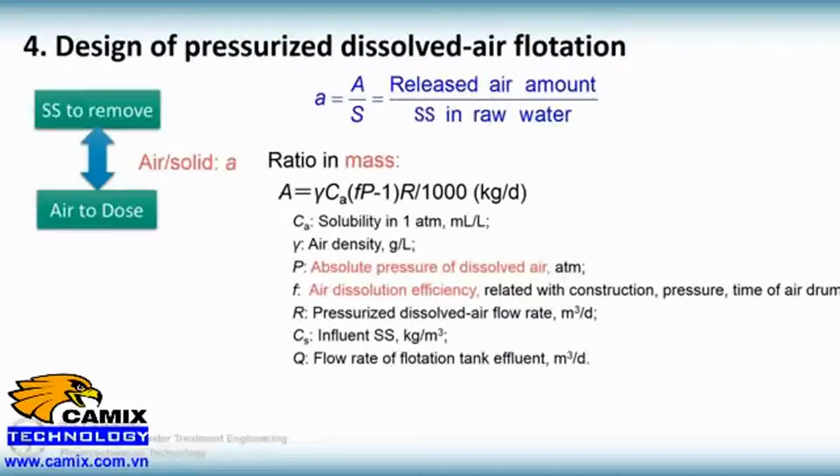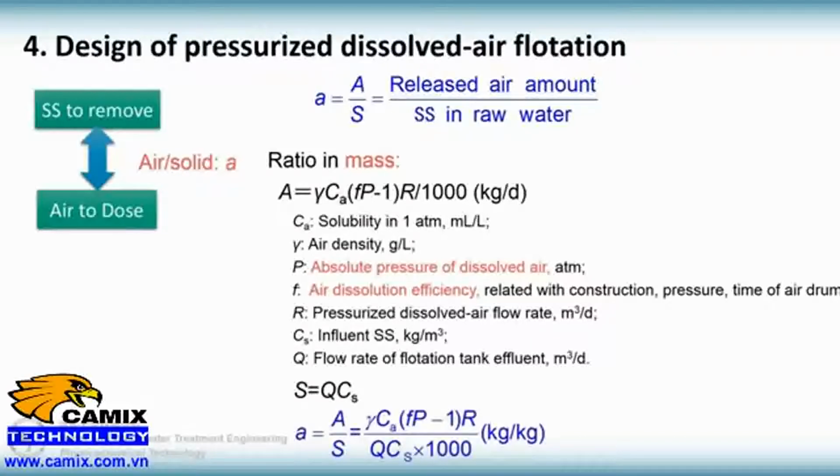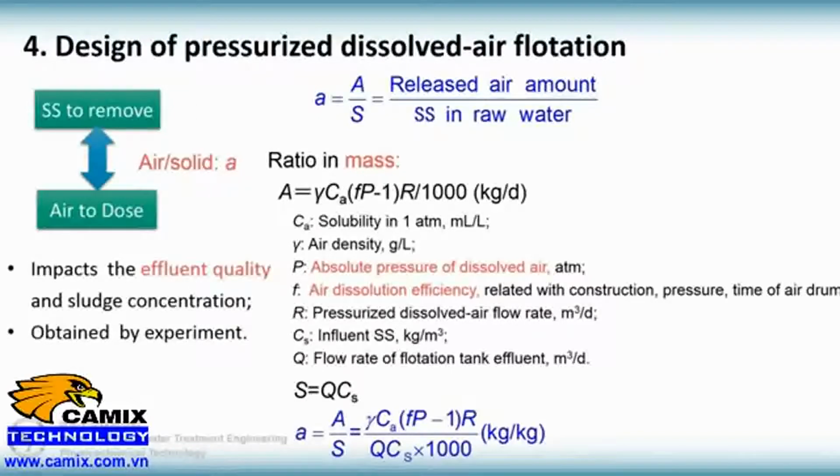Total suspended solid S brought in by raw water could be calculated by this equation. So we can present gas-solid ratio as this equation. Gas-solid ratio is an important parameter affecting flotation performance. It affects the effluent quality and sludge concentration. Its value can be acquired through experiment.